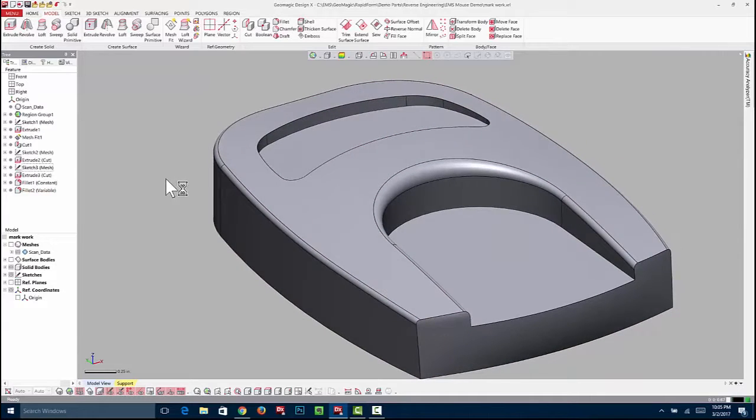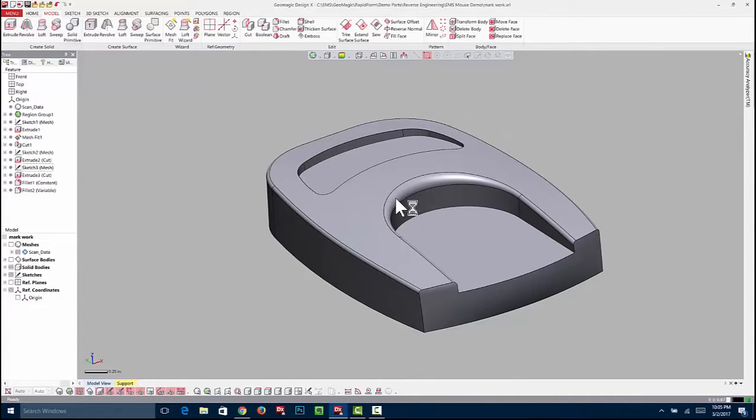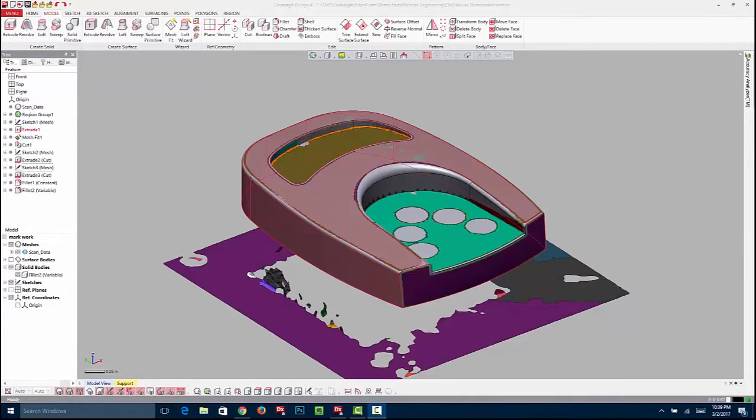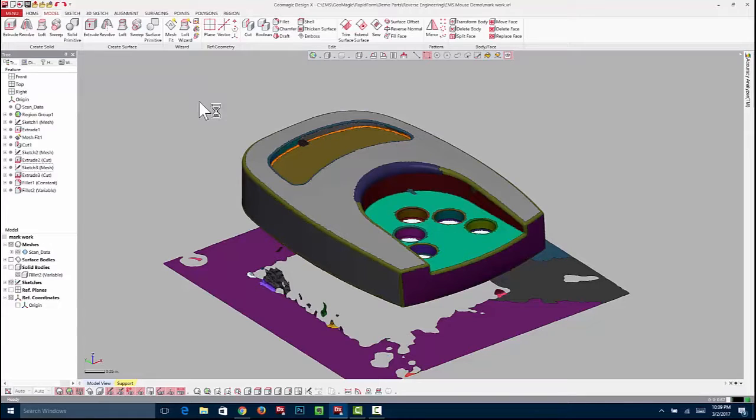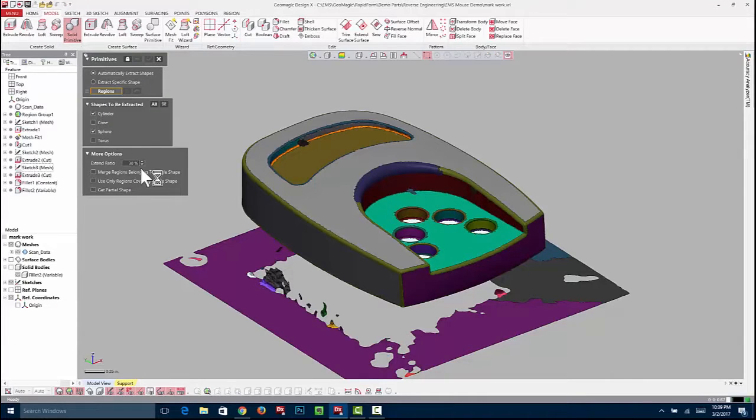So it's very easy to do a lot of this more complex geometry. Okay, so next we still have these cylinders in here, and let's use another command. Now we could certainly cut another section and just make 4 circles and extrude them, but just to show some of the commands in here, we can generate solid primitives from some of the geometry.